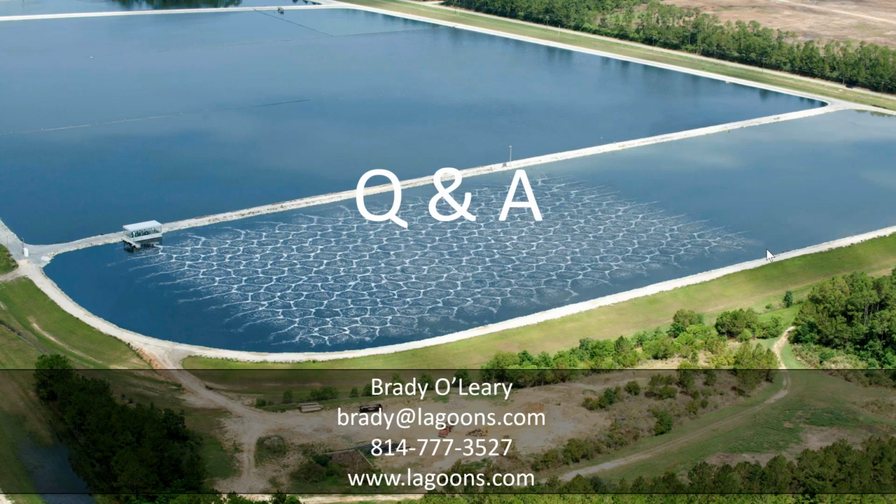It's kind of a sticky issue depending on how much sludge you have, and what the concentration of organics is in that sludge. Is it mostly grit and ash, or is it more like undigested carbon? You can do some studies to determine that. I do believe we have some webinars specifically on sludge. They'll go into much more depth here. But you can also do sludge removal. In general, lagoons are designed to have sludge removed every 10, 20, 30, 40 years. And most lagoon systems have not been keeping up on that regimen. So starting over, getting rid of that sludge, can be very costly.